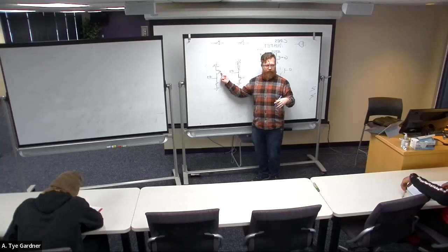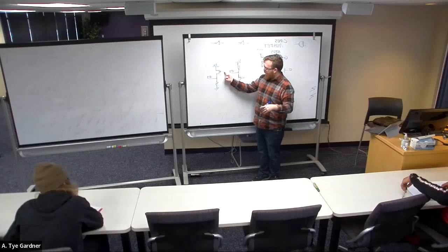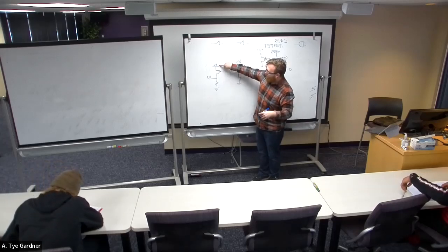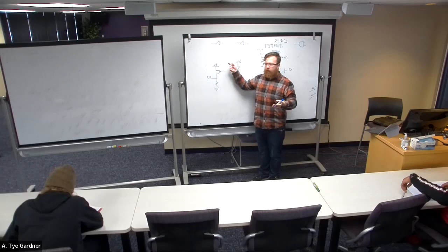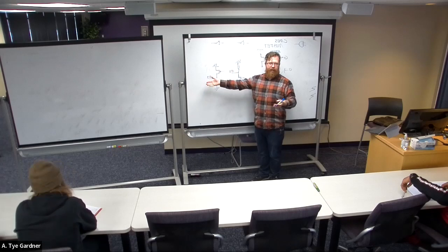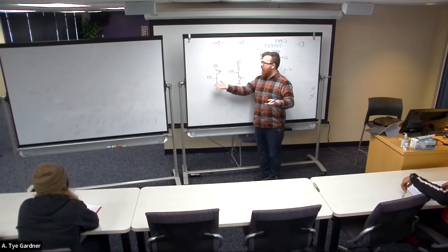We know that from this little inversion bubble. So I put a 0. There is a connection between VCC and the digital signal. There's no path to ground, it's just a closed switch, meaning the digital signal becomes a 1. So I input a 0, output a 1, input a 1, output a 0. This too is an inverter.